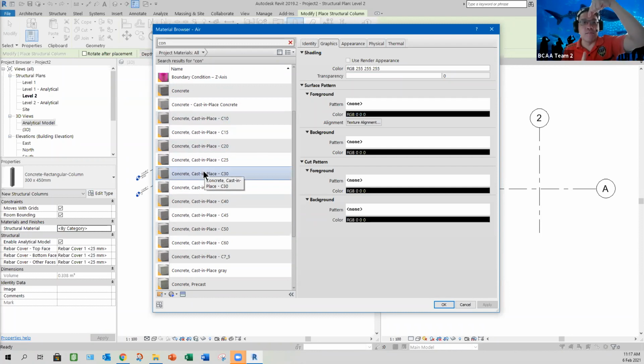They have certain so-called load bearing calculation, and of course your rebar cover kind of thing. In Singapore, the engineers use C35 to do the calculation for structure buildings. Basically this is the average one. So C30, you pick OK.